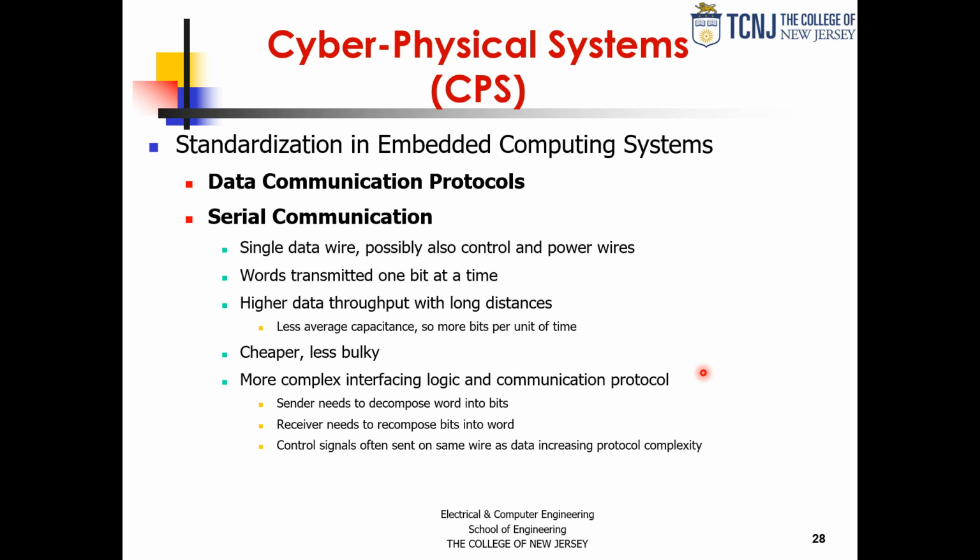Inside the chip, let's say, the data is parallel, so you have to be able to serialize that data, send it out at very high speeds, grab it at those very high speeds, and then deserialize it. Those modules are called SERDES, serializer deserializers.